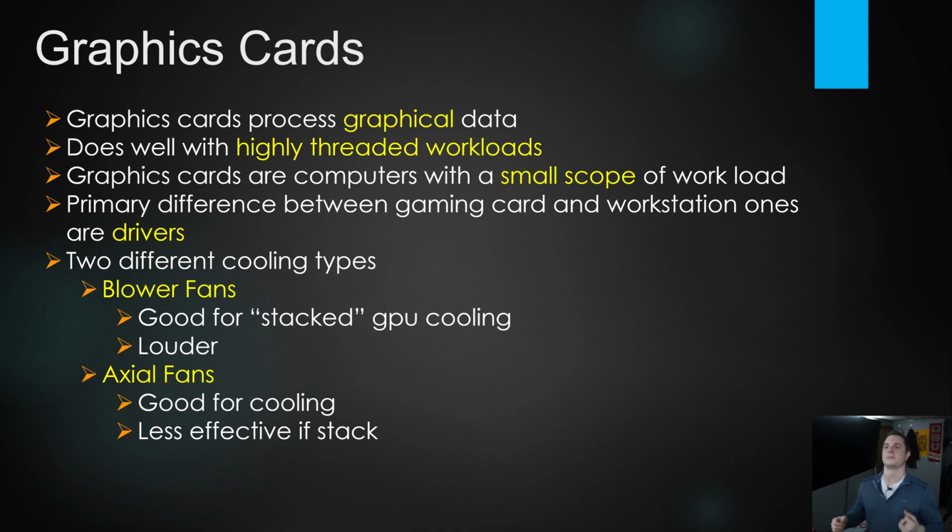Okay, so there's also another big difference between your consumer and professional level cards as well, and that comes down to cooling. So axial fans is what you find on your consumer cards. They're pretty good at removing heat, but it goes directly into the case itself. So our consumer cases are designed to handle that, and it's going to be no problem. If you have axial fans in a server, it can be done naturally, but there's more to consider. So if you put it right up next to one of the sidewalls, you're going to choke out that fan, and it's not going to perform very well, and it's very likely it's going to overheat.